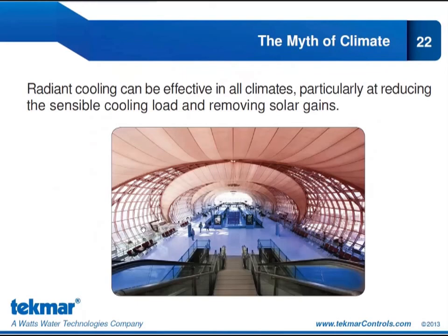So this was a very well designed, implemented radiant cooling system where it was done in a location that is very hot and humid, but done in such a way that it was only trying to remove the solar gains and not provide any latent cooling. So a forced air system is of course still needed to remove that humidity in the space, but we can reduce the overall cooling load by whisking away those solar gains with the radiant cooling.